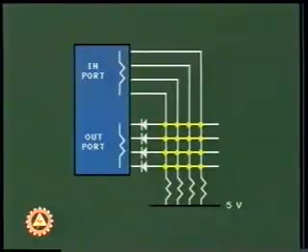Let us take another example to understand the division of tasks between hardware and software modules. Let us consider a 4x4 key matrix being used to enter commands and data into the microcomputer. We can recognize a key being pressed by using two 4-bit ports. A logic 0 is passed on each output port line sequentially, and the status on the input port is read.